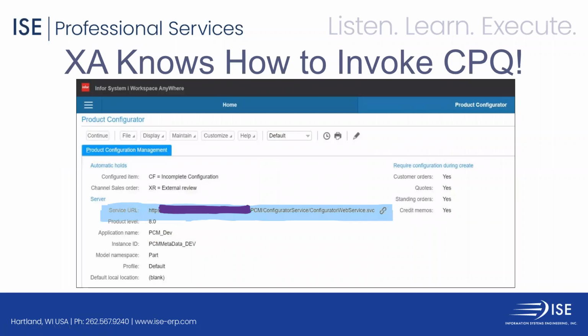XA knows how to invoke CPQ in the product configurator entry in the applications business object. That's usually on the environment tab. You have to give the service URL. I marked out the host machine name and domain name for privacy purposes, but you actually establish the URL that XA will use to launch CPQ. So XA knows exactly how to invoke CPQ, and a brand new window will pop up. If you're running NetLink inside of System I Workspace, especially inside of Infor OS, then the XA tab and the CPQ tab actually appear next to each other.